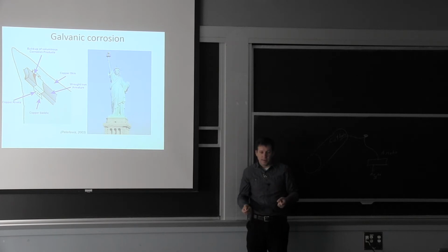So when you're thinking about a fastener going into an assembly, that's the component that needs to be the strongest. So lots of times we will use stainless steel if we have dissimilar material for bolts or rivets, just because we want to make sure that this smaller component doesn't consume a lot of the galvanic reaction.